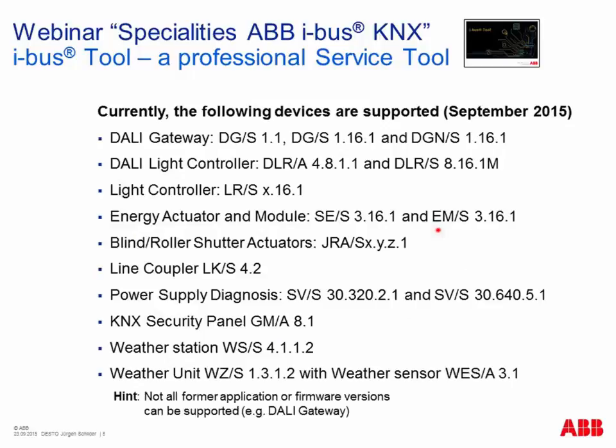So what is supported at the moment, the current status: the DALI components, both on the DALI side for DALI addressing, for assigning DALI groups, important, but also for the light controller solutions to calibrate constant light control. So here it's more or less a must to use this IBAS tool, and it makes life much easier than using the ETS only for doing this job. Our energy actuator, energy module, Jürgen will come to this a bit later, metering in principle, a very simple way to display the measured values.